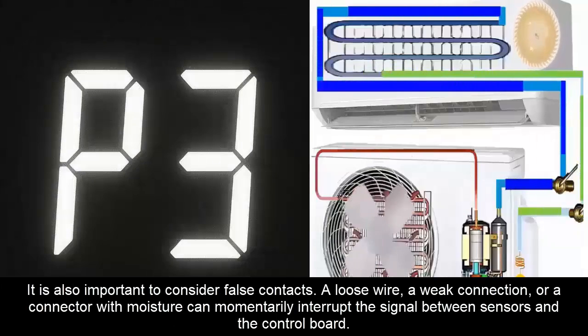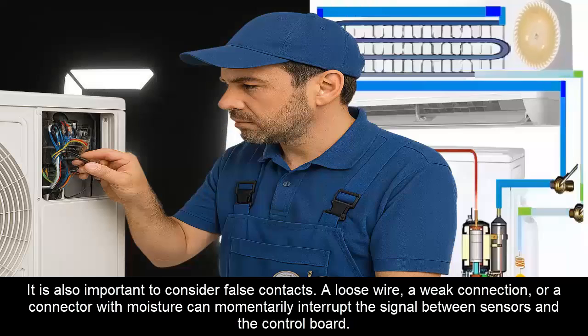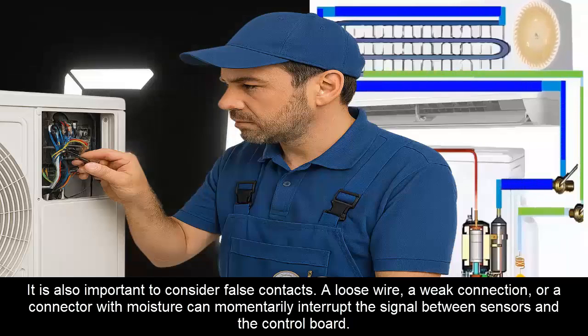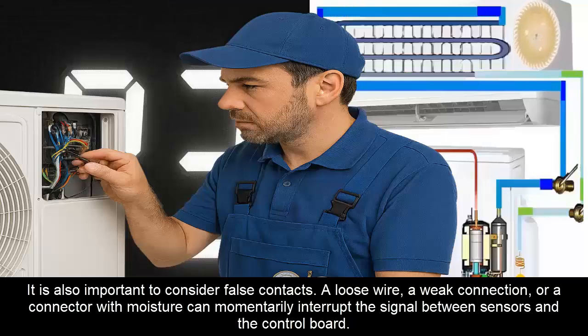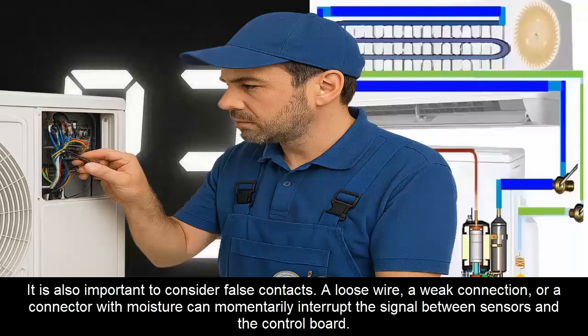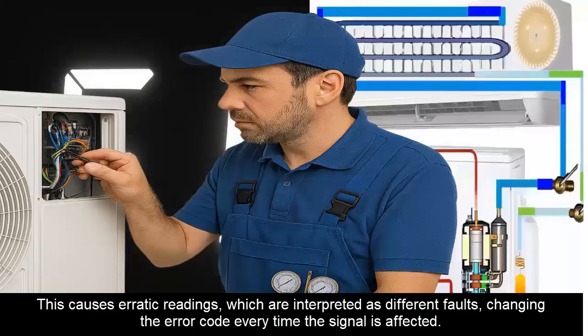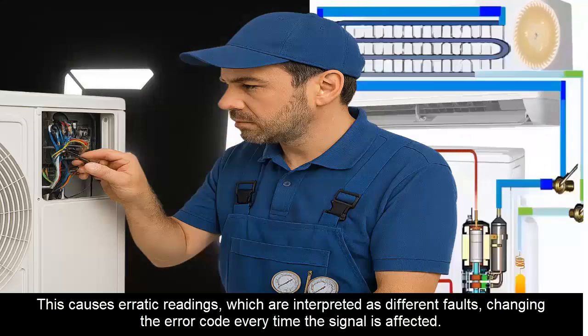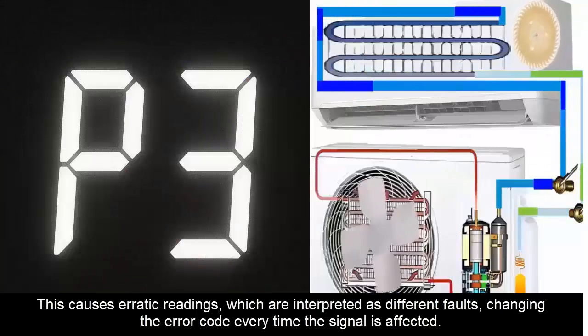It is also important to consider false contacts. A loose wire, a weak connection, or a connector with moisture can momentarily interrupt the signal between sensors and the control board. This causes erratic readings, which are interpreted as different faults, changing the error code every time the signal is affected.